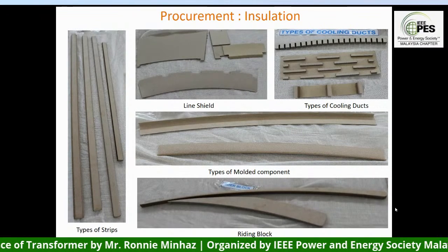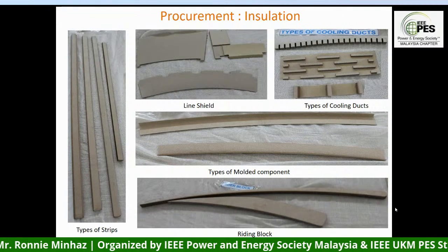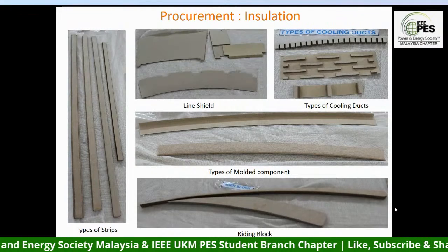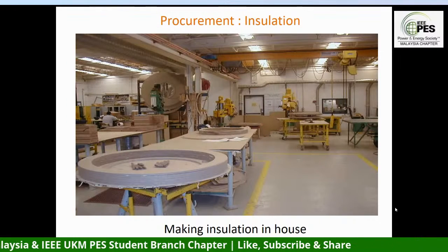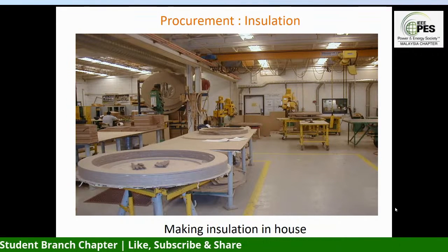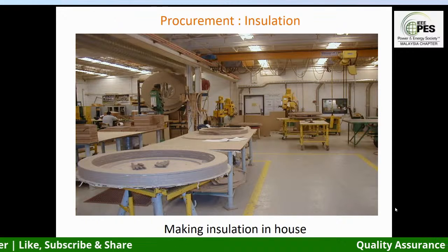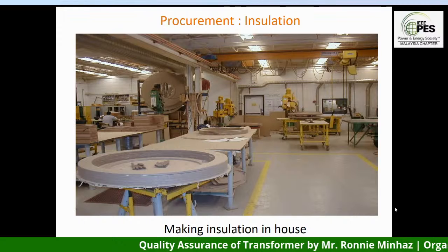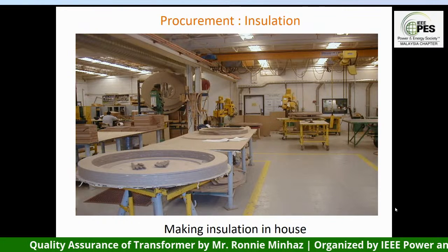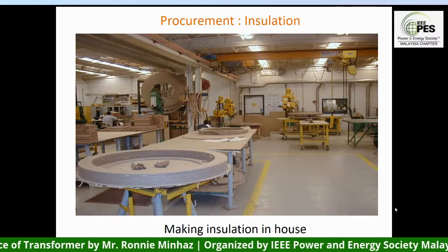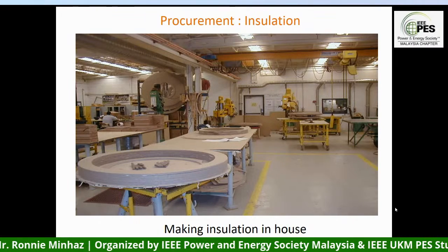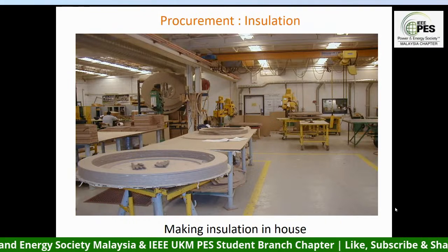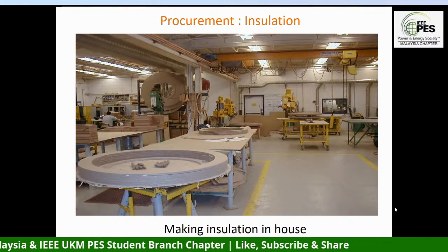The manufacturer can say, you know what, I will not buy those things as pre-cut from a third party. What I will do is buy the insulation in bulk, and I will use what we call an insulation shop in-house, and I'll cut the insulation in this shop. Now the question is, look at the floor, is the floor clean or not? If this floor is not clean, if this room is not climate controlled, if this room is not humidity controlled, what will happen? This insulation will absorb moisture and it will pick up dust and all those things.